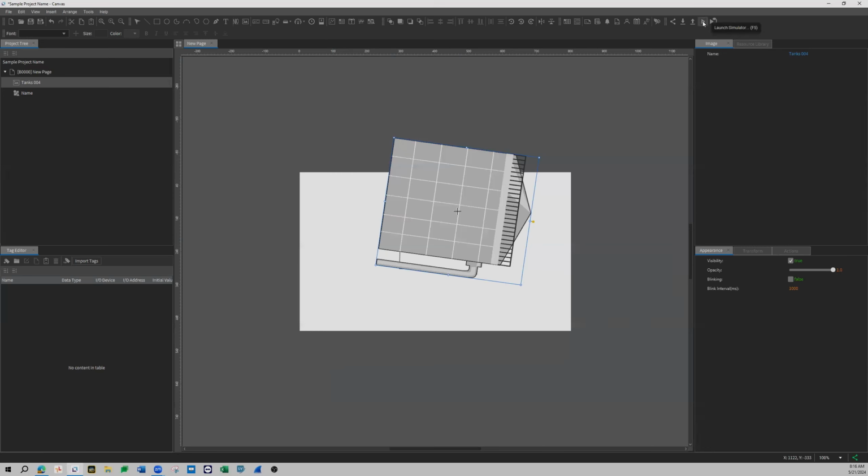And then if you don't want to connect to PLCs or field devices from your computer, you can just use the normal simulator, which is over here, to the left of it. But keep in mind the online simulator only lasts for 30 minutes and then it will turn off. It'll just stop working. So what you can do is close it and reopen it and that will refresh that 30-minute window. Basically we're preventing people from abusing the online simulator by continuously letting it run on their computer.